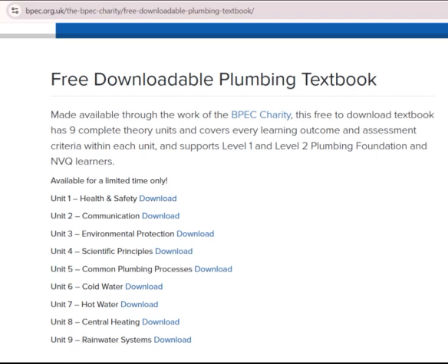AC 2.5 state the general operating principles of solid fuel-fired heat producing appliances. Solid fuel is still used as a heating fuel in some remote areas where there is no access to a piped gas supply. There are several forms of solid fuel, including coal (high carbon, high sulfur content), coke (smokeless, high carbon content), anthracite (high calorific value, high carbon content), and biomass wood chips and pellets (carbon neutral fuel).